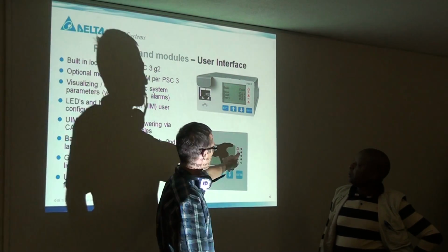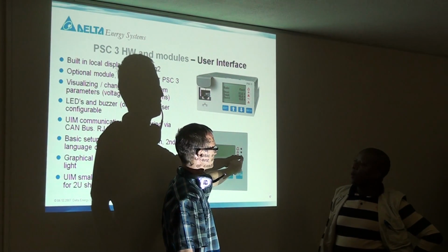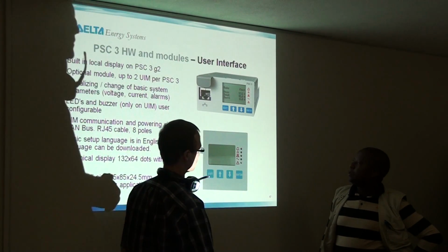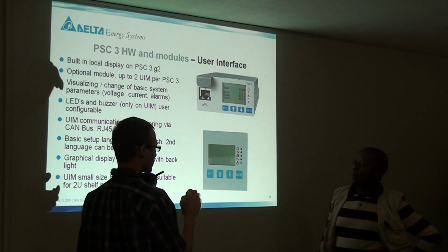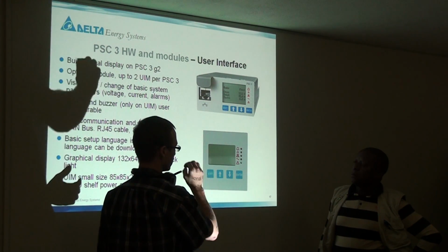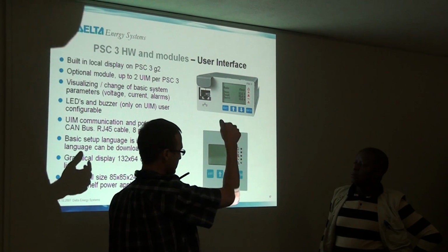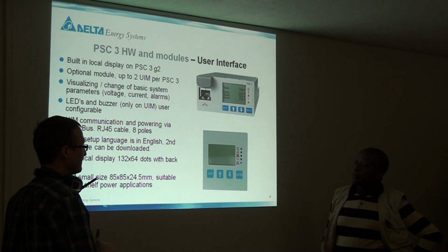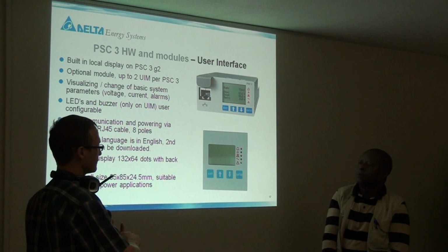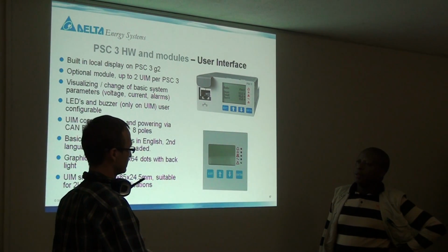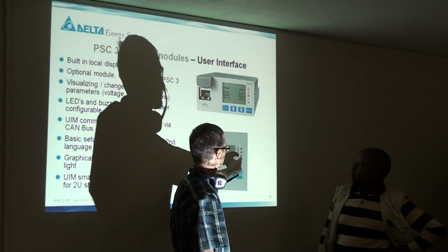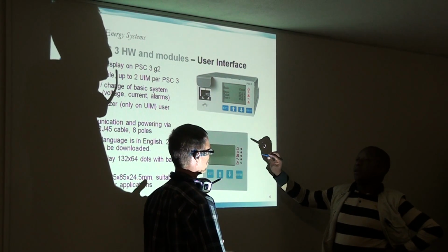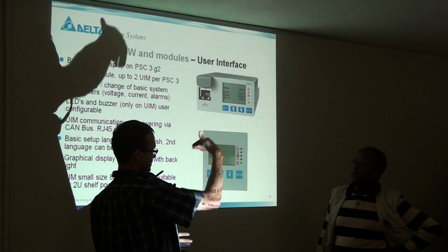That means the alarm will still be there, but you stop the transmission of the alarm, and you don't flag it anymore, so it doesn't keep sending you. You can do it with any one of your alarms currently configured into your system, individually as well as in groups. So you can set an alarm, you can reset an alarm, you can stop or force an alarm to be off, and you can put it in normal condition. It'll display this. So this red line means your alarm has been forced. Then you fix it and then you force it back to normal.